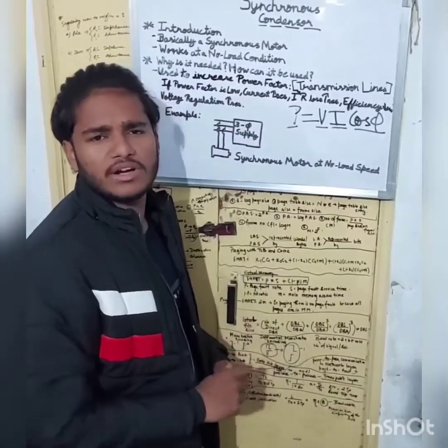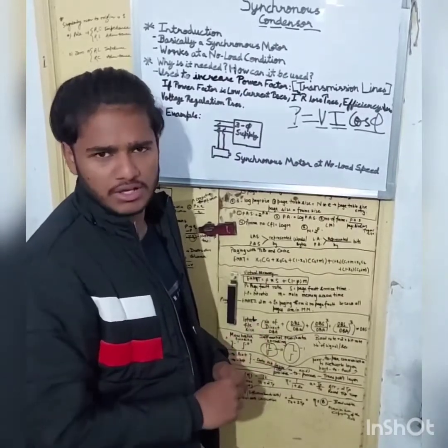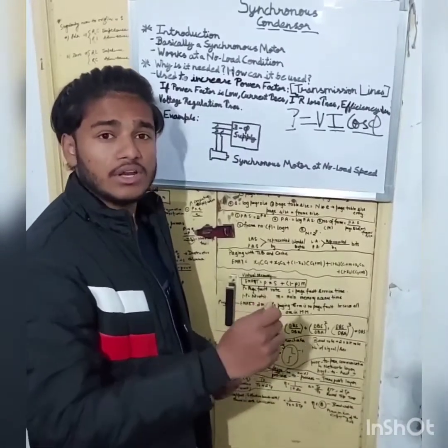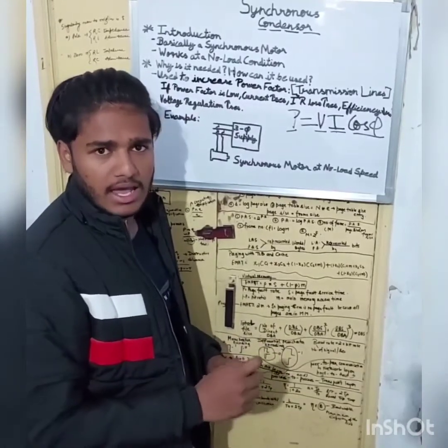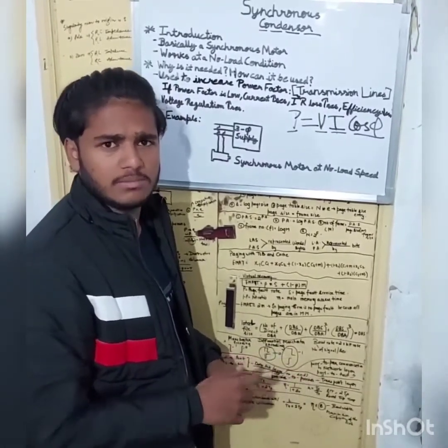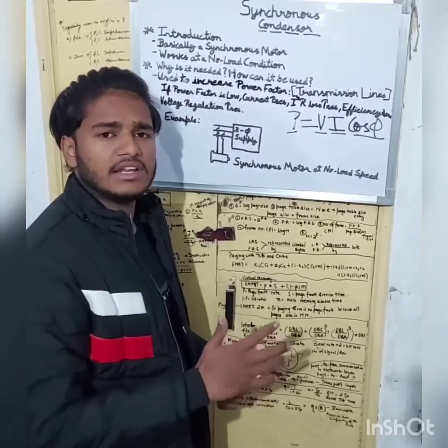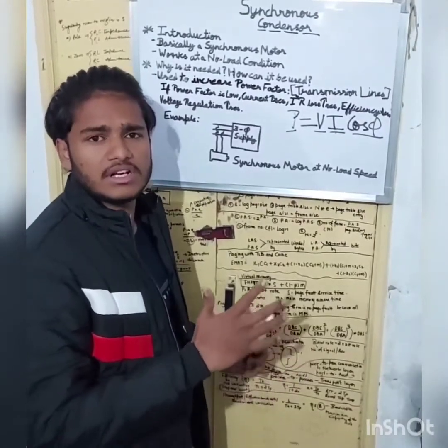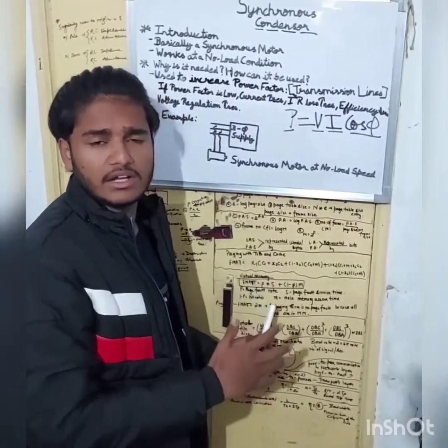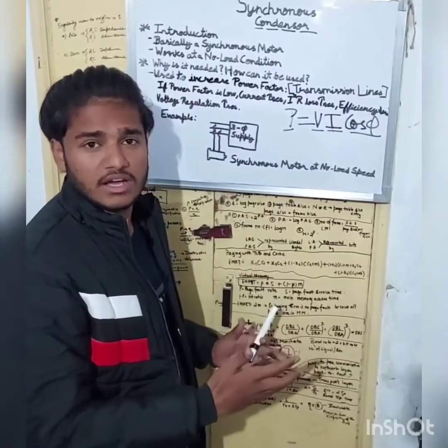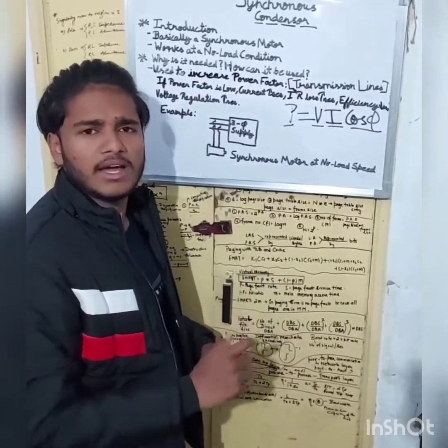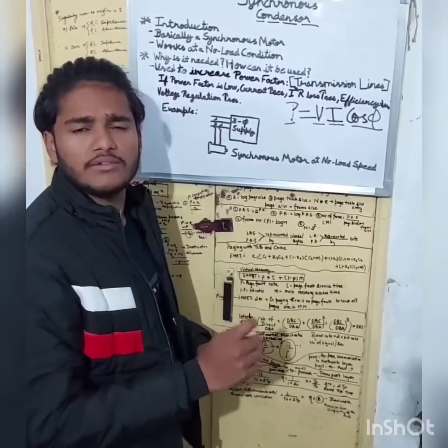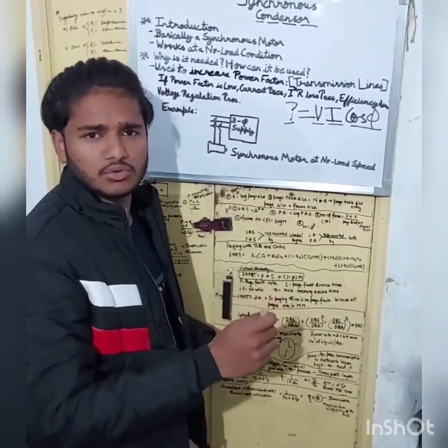One more important thing I would like to point out here is that the voltage regulation also increases, which is undesirable. Voltage regulation basically means the difference between the terminal end voltage and the no load voltage, thus causing more losses. Again, bad for us. So the bottom line is, the closer the value of voltage regulation is to zero, the better.